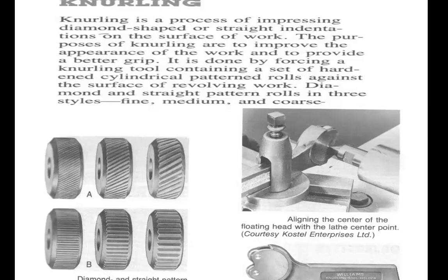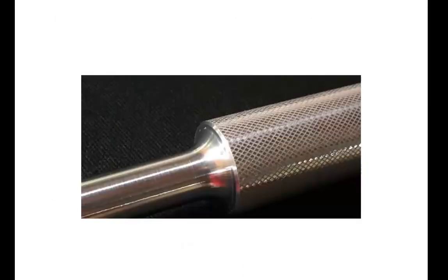Yes, in most cases, if it is the handle part, to hold and rotate, then to be able to increase the effect of friction, to have a better gripping, well, yes, we create a certain pattern over the surface. Using the knurling tool, applying the necessary deformation force, we create such a pattern over the surface.